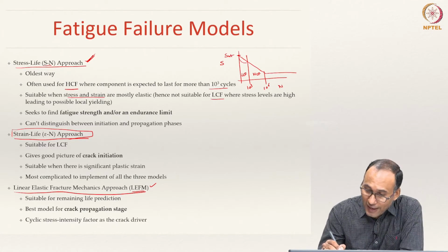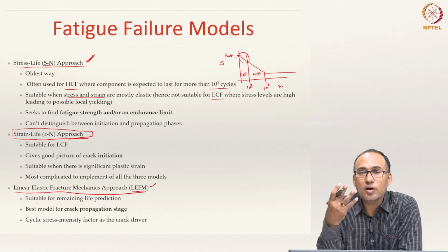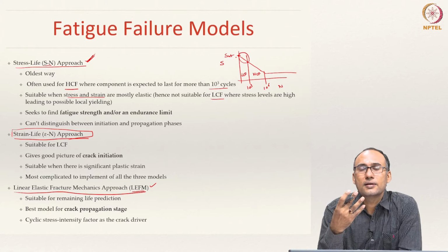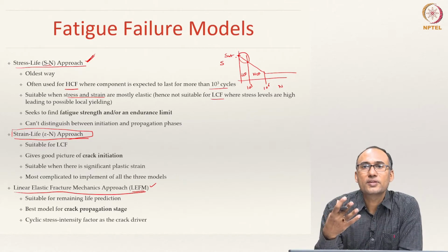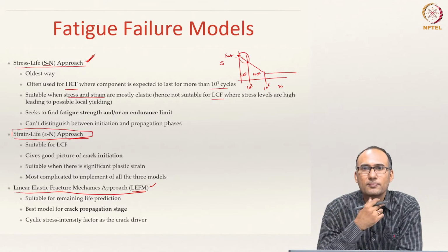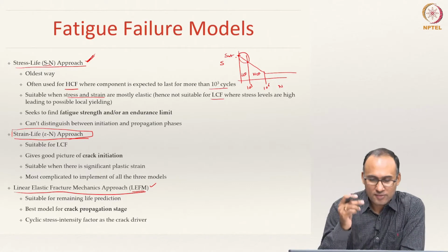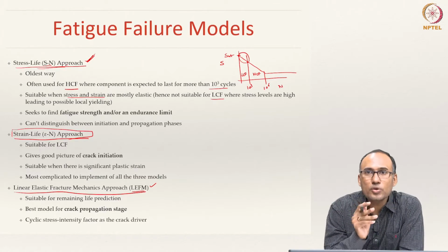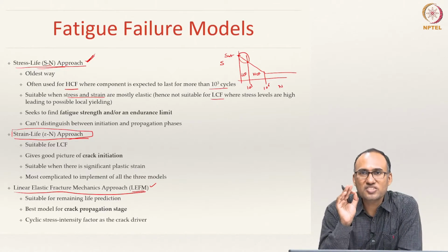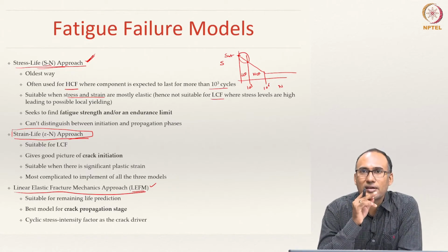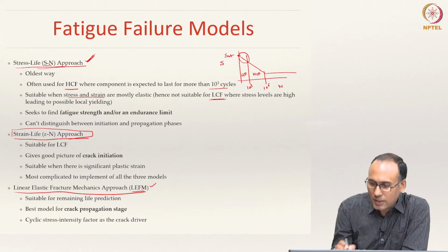That means the magnitude of the stress experienced by components under low cycle fatigue is usually very high, and as a result there is a higher probability for these components to experience plastic deformation, right? And hence the stress life approach is not suitable, because it assumes elastic deformations, or stresses being elastic, when we are doing the analysis, and hence it is not suitable for LCF, that means low cycle fatigue.